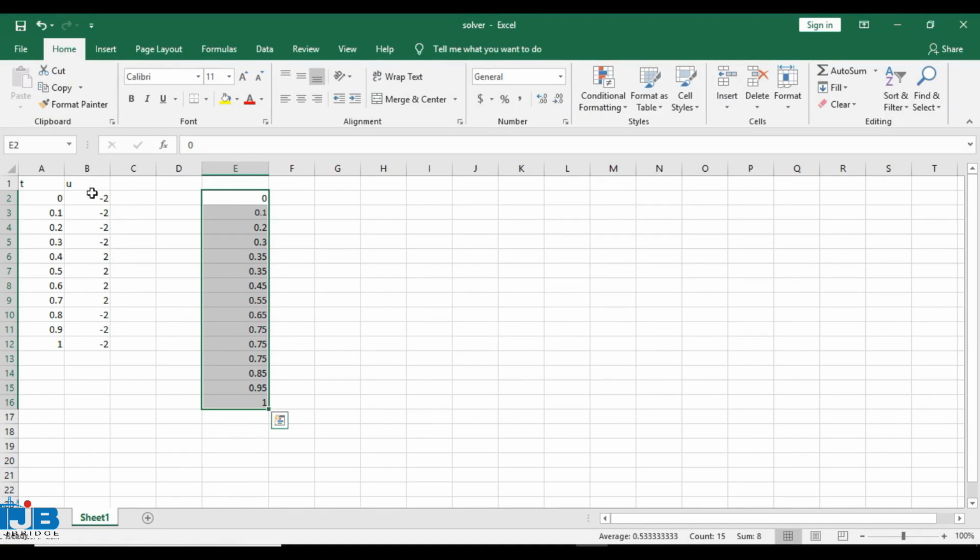As you can see, I have just given a fixed step of 0.1 time input, but here it is taking multiple at 0.35 and 0.75. There are 2 entries for 0.35 and 3 entries for 0.75. So as you can see, the variable step size solver takes more, like it is taking 15 steps while I have defined just 11 steps. So this is variable step solver.